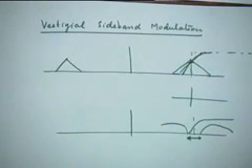However, there are certain kinds of signals which have a lot of low frequency content, and which are sensitive to phase distortion. And one such set of signals is the picture signal I mentioned to you. So you have picture signals, you have facsimile signals, which are also kind of picture signals. You are scanning the content of a page. So all these signals are very sensitive to phase distortion, which will occur if you try to implement an SSB modulator.